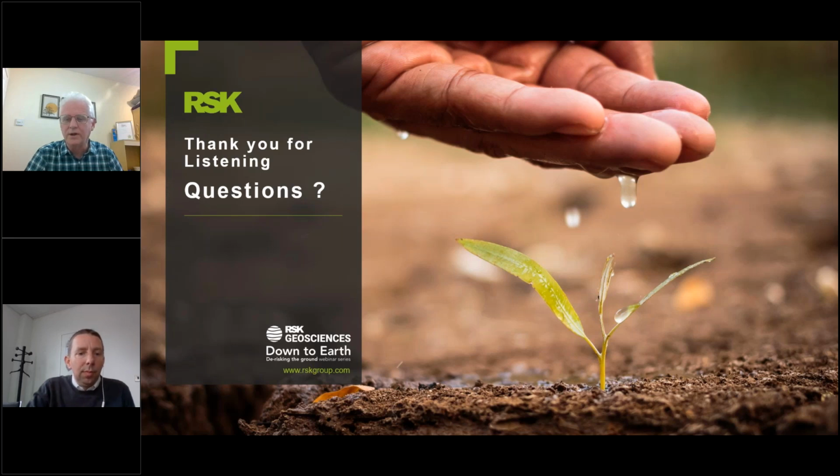First of all, what do you do if you have a tree nearby, looking at the NHBC guidance, that is not on the NHBC tree list? Well, if there isn't one on the list, then an arboricultural survey, I would say, would be the first port of call, because they could then rank it into a category in terms of its expected mature height and its water demand in particular. And we do have people within RSK that can do that kind of survey work.